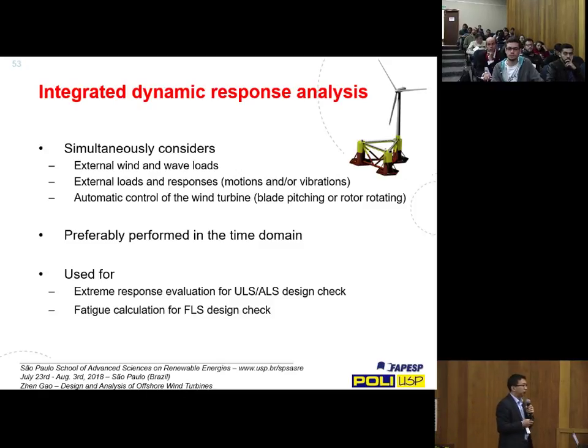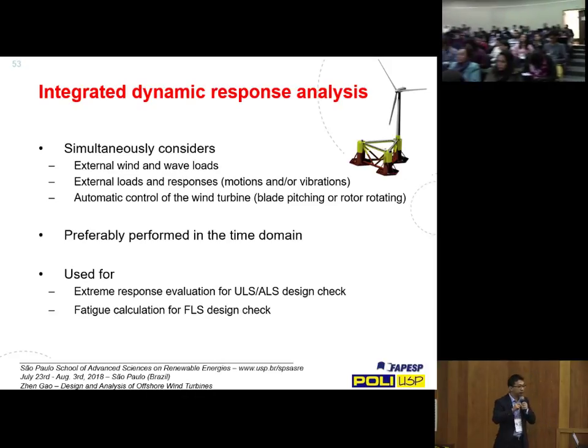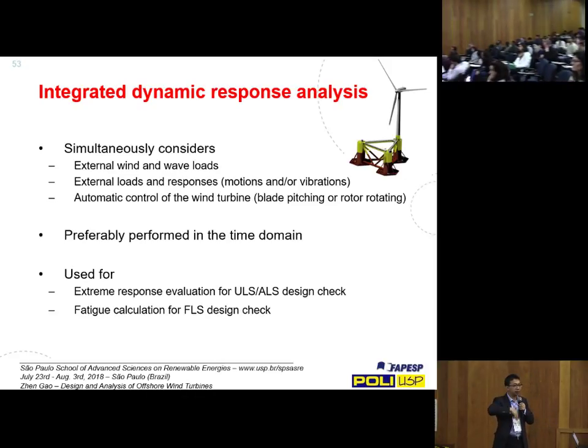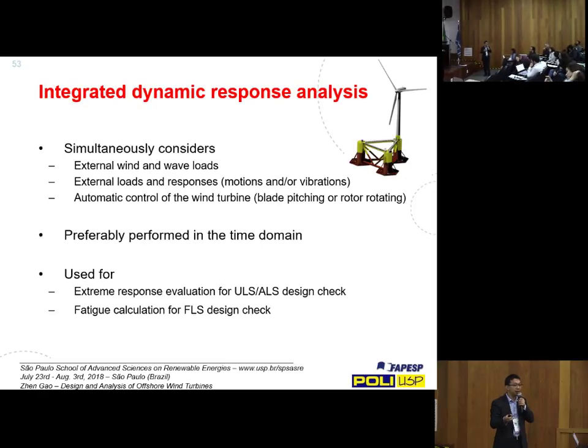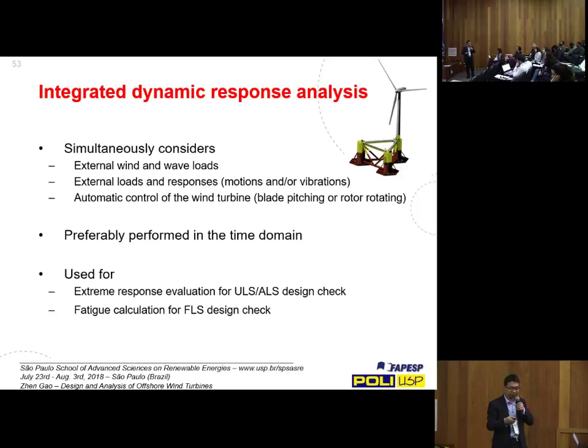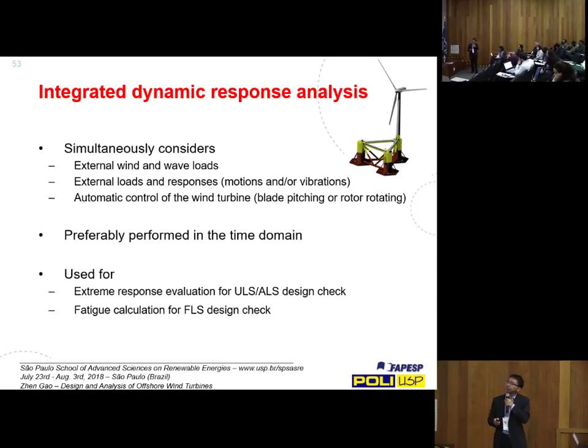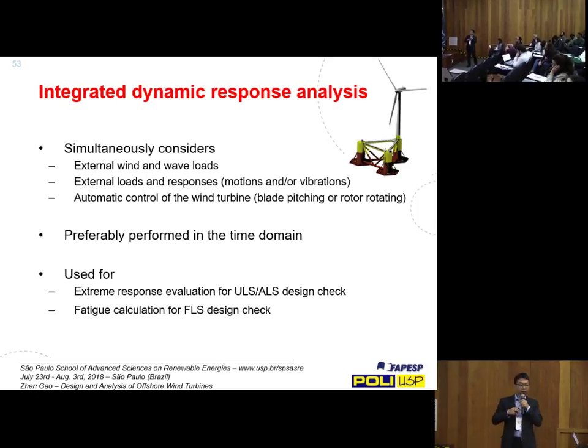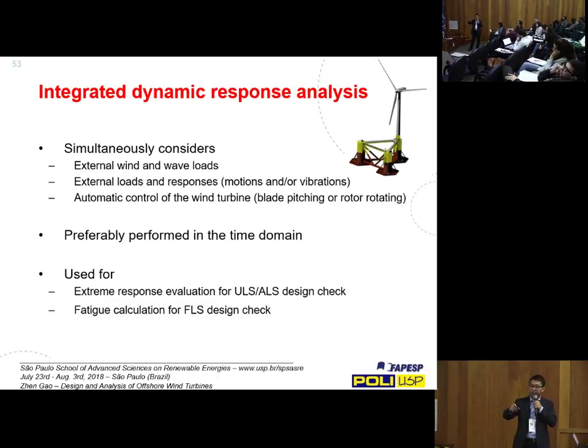So when you get all of the loads, the wind turbine loads acting on the blades, and hydrodynamic loads on the floater, and I also forgot to mention that for mooring lines, you also use Morison's formula to get the loads on the mooring line. And then all the loads are acting in the same system, and then you have to do the response analysis.